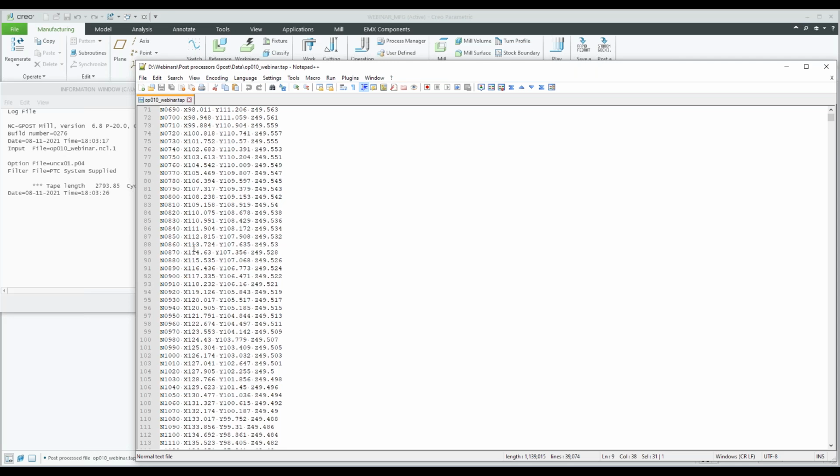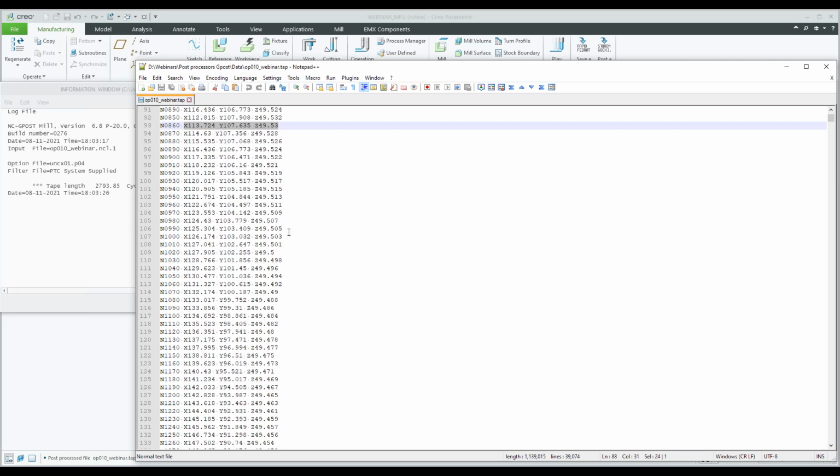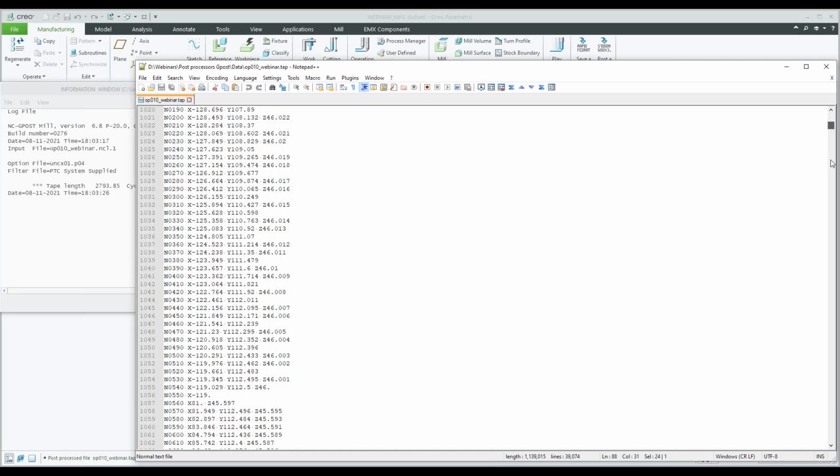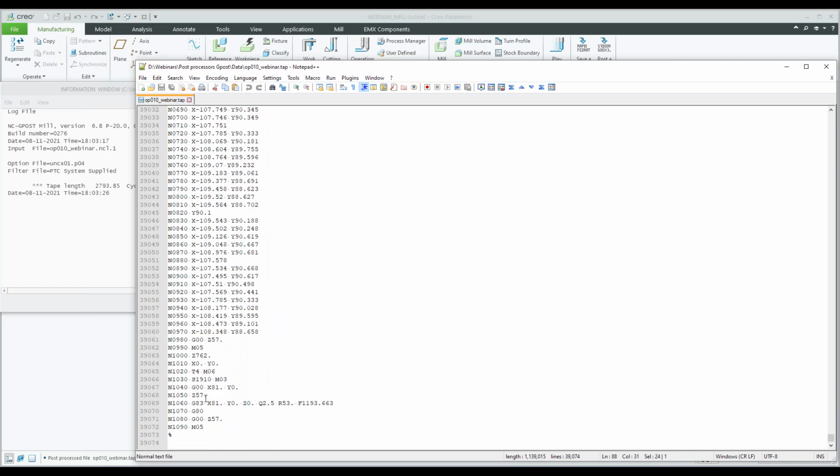for a 3-axis machine. The first one is up and down all the time. It's got some small Z moves here. Okay, not ideal. Let's go to the bottom. Let's just check that drilling. Okay, so these are G83. It's giving us a Q value.